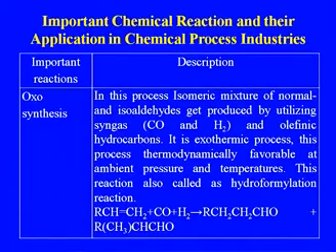Oxosynthesis: in this process an isomeric mixture of normal and iso-aldehydes gets produced by utilizing synthesis gas and olefinic hydrocarbons. It is an exothermic process. This process is thermodynamically favorable at ambient pressure and temperature. This reaction is also called the hydroformylation reaction.